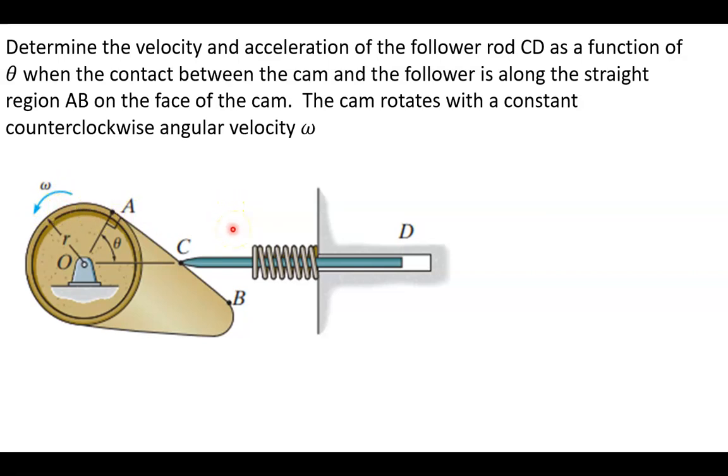Alrighty, and as you know, the principle behind the cam is to take rotary motion and translate it into linear motion. So that's what we're concerned with. And you can see, like I said, this is a right triangle. Again, that's going to become important as the equation goes on, and we're just concerned with the rise portion. That's known as the rise portion of the cam. And this is the direction that the follower is going to take.